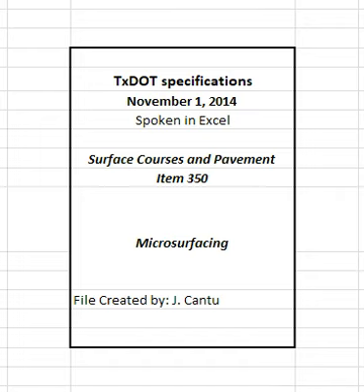3.1 Mixing machine. Furnish a self-propelled microsurfacing mixing machine with self-loading devices to promote continuous laying operations. Enough storage capacity for mixture materials. Individual volume or weight controls that will proportion each material to be added to the mix. Continuous flow mixing with a revolving multi-blade mixer capable of discharging the mixture on a continuous flow basis. Opposite side driving stations. Full hydrostatic control of the forward and reverse speed during operation.